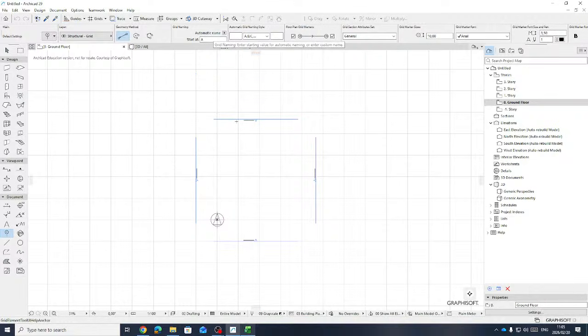Now we use letters in one direction and numbers in the other. The reason is if the contractor phones you, there's a problem on this grid. If the building's at an early stage, they're going to give grid references that you need to go and look at a room. Because there are a lot of situations where a room's not quite in a location, it's hard to explain over the phone. The engineer will say grid A1, you go straight there, it's easy. Okay, so we're going to use letters first.